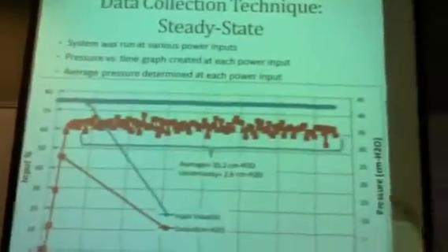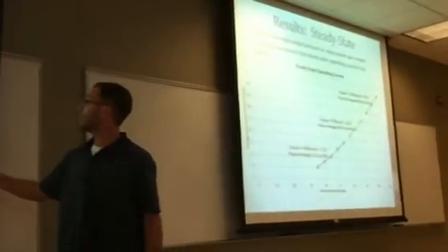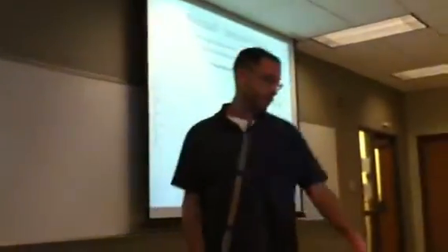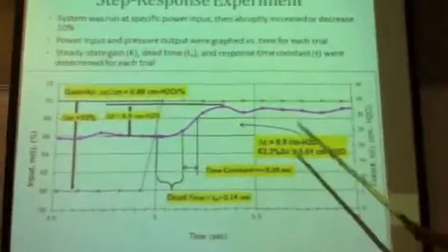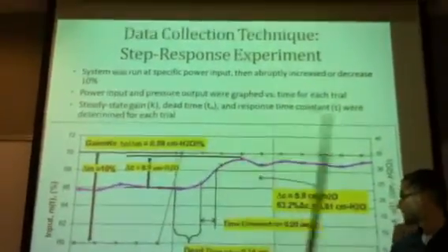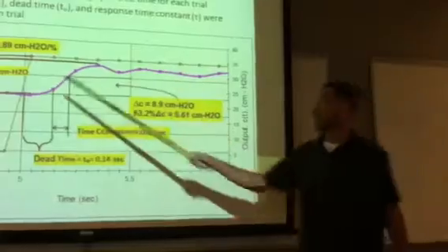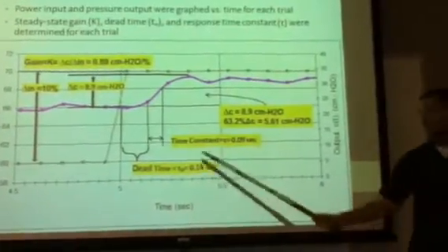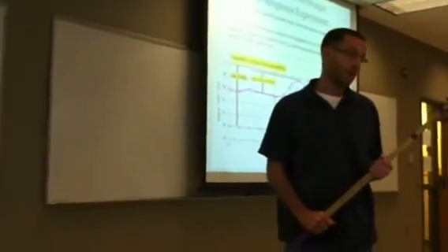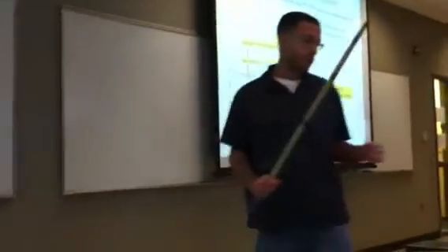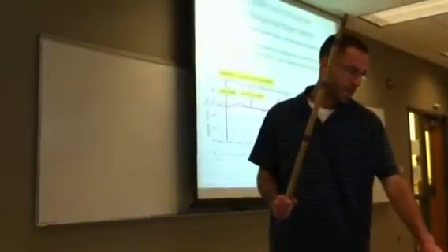This is our steady state plot, and our steady state operating curve for each of the 3 ranges: low, middle, and upper range. This is our step response experimental, where we ran step ups and step downs to figure delta M, delta C, and then eventually gain, time constant, and dead time, which are going to be the 3 parameters of our system that we've calculated various ways throughout all our work up to date.